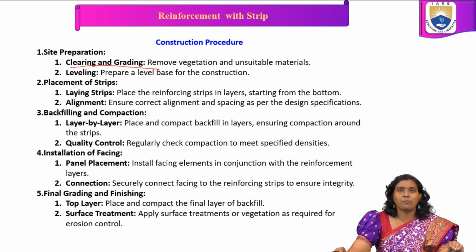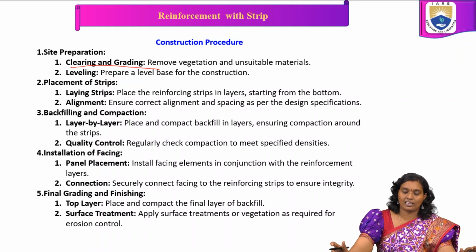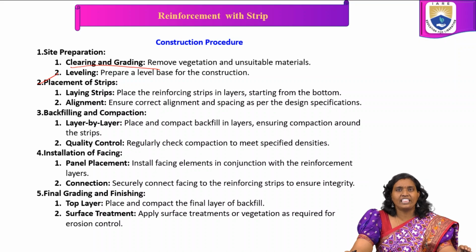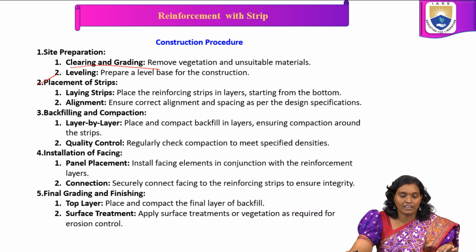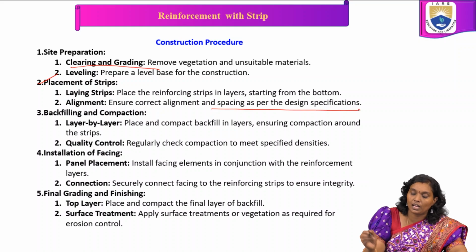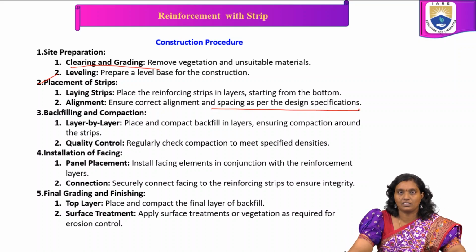And leveling: prepare a level base for the construction. Now, in placement of strips, these are the parameters for laying the strips. Place the reinforcement strips in layers starting from the bottom. In alignment, ensure correct alignment and spacing as per the design specifications.